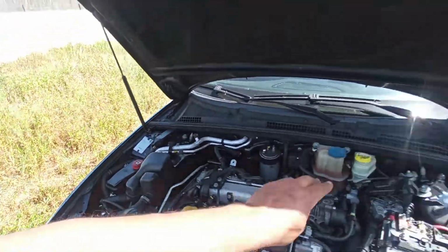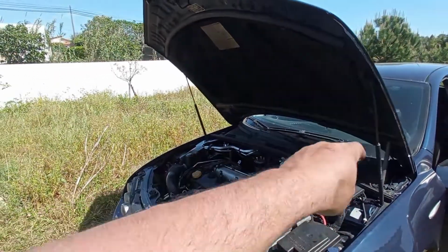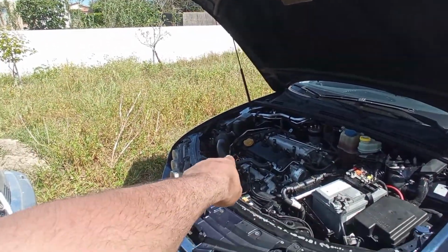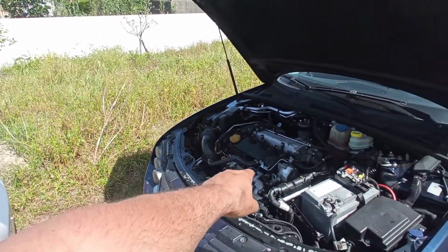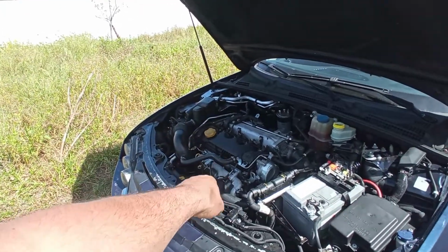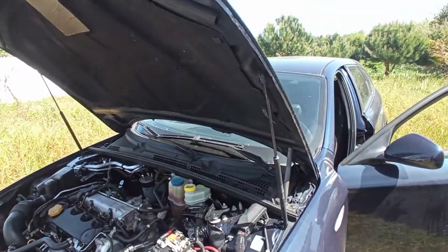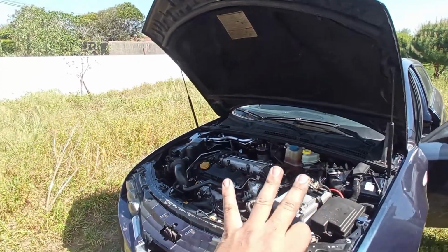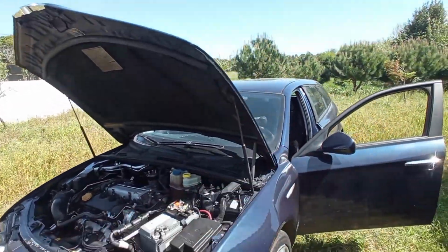Okay, let's just see if the DPF procedure is accepted or not. If so, we can continue to read the parameters. I want to read the quantity of air. I want to see also the pressure of air, and I want to see the back pressure of the exhaust. Those are the three main things that I'm going to see now on this car because of the DPF's problem.